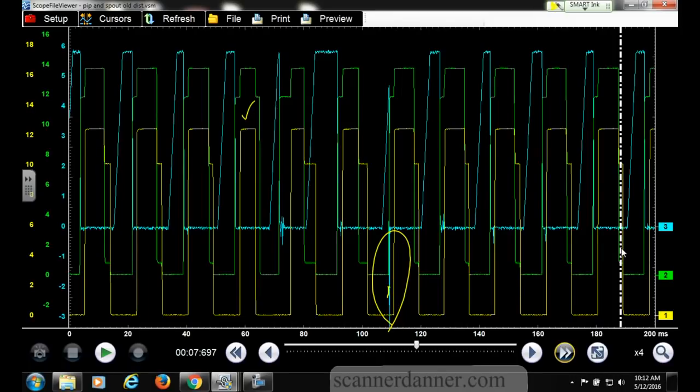Yep, and so you're looking at that right there. After this guy, right? After this guy, then the next one has this long cutout in the PIP, which gives me a really long coil dwell time. And then the immediate result of that after is a really short one, and that's the one. This is the one that's really causing our number 2 misfire.